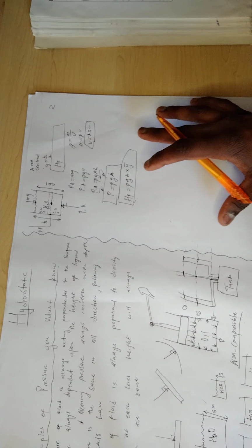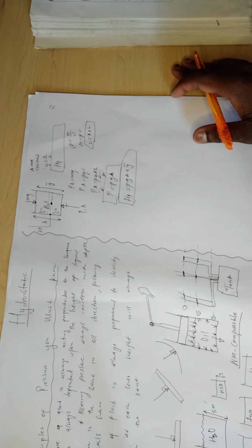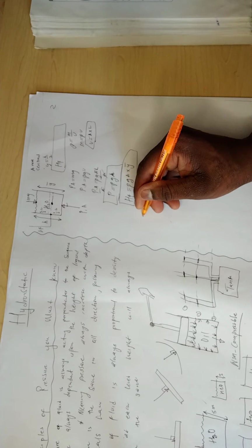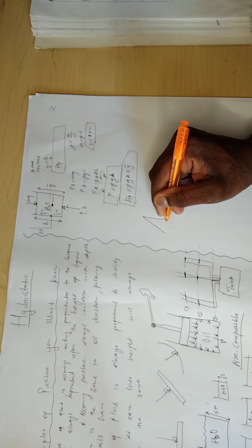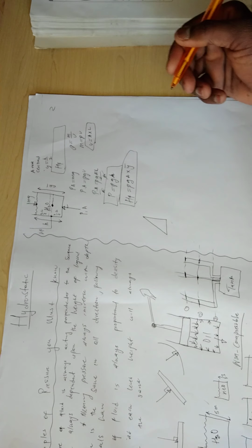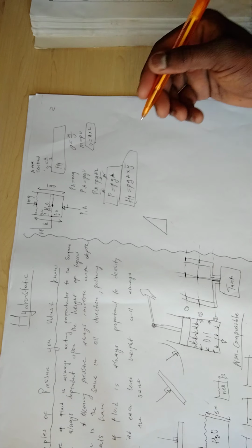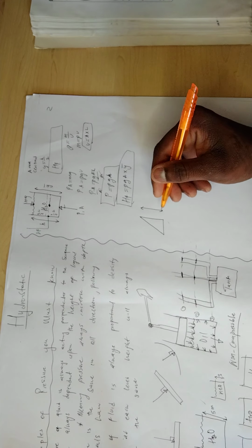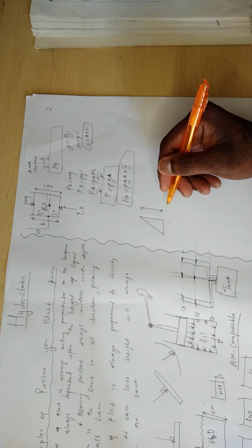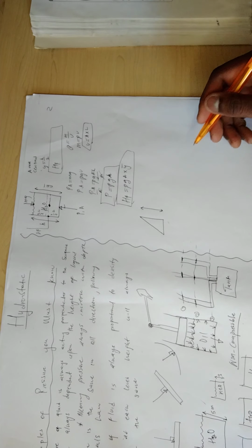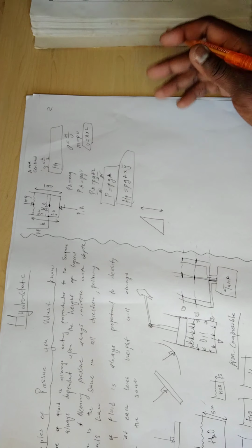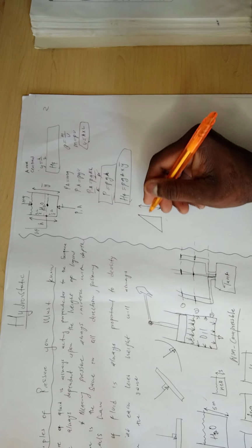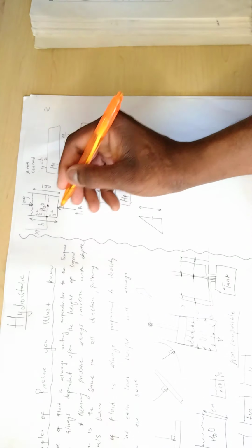So we can proceed and look at the scenario where we are given a triangle shape. If we are given a container that is in a triangle position like this, you must always take note that the height will be this side. And when you look at the centroid, it will always be your height divided by 2, and where your hydrostatic force is going to act will remain the same as with this one.